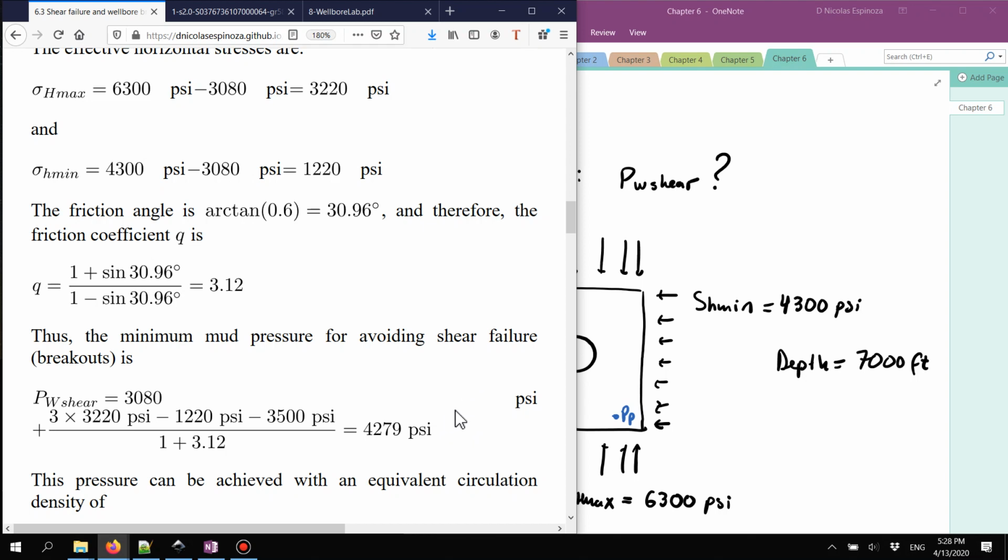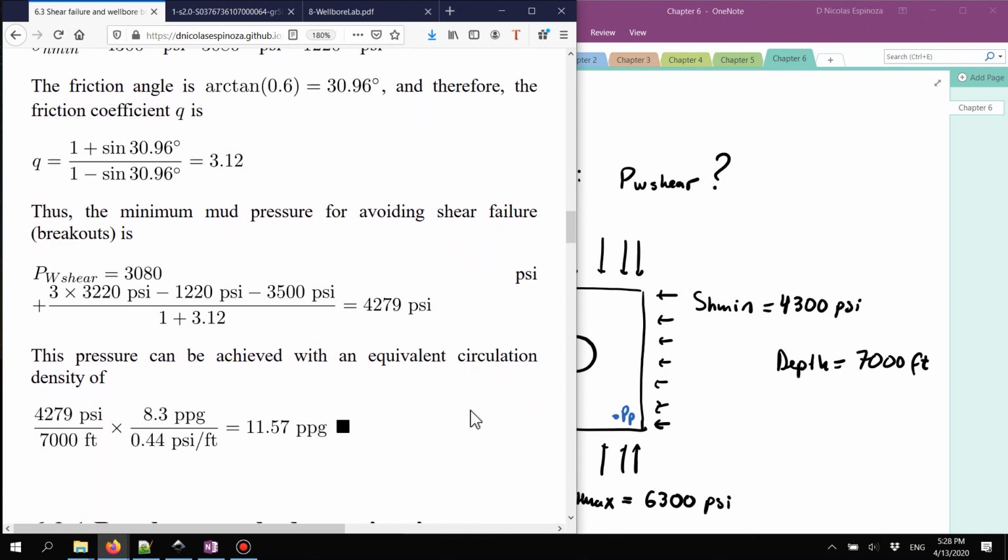How do we compute now the mud weight? Well, what we're going to do is assume that we have a hydrostatic column of mud weight, and that will mean that there is no managed pressure drilling. For those of you that are taking classes in drilling, we know that sometimes we can modify the pressure in the wellbore if we change the pressure on surface or at a given depth within the wellbore. Well, in this case, we are not going to do that. We're just going to assume there is a hydrostatic column along the wellbore.